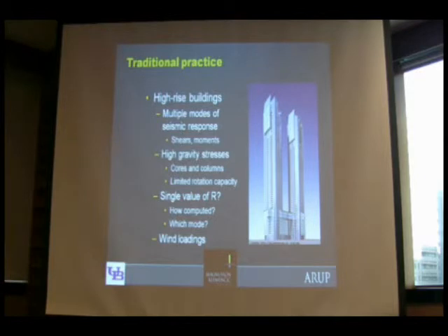and the overturning. But in tall buildings, we see that there are multiple modes of response that are critical to the base shear and critical to the overturning moment. One will often find that the first mode response will drive the overturning moment, which would influence the design of the core, the flexure, yet it's the second or third mode that might produce the maximum shears, which would influence the shear resistance of the core, for instance. So our traditional procedures, our first mode procedures, are inappropriate for tall buildings where multiple modes control the seismic